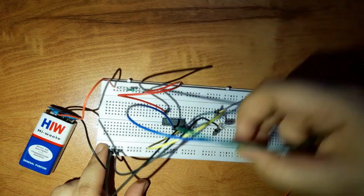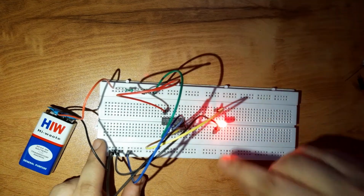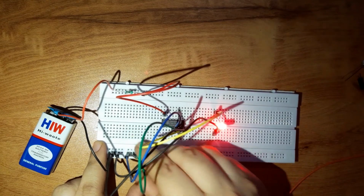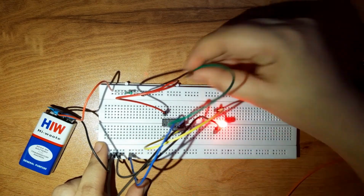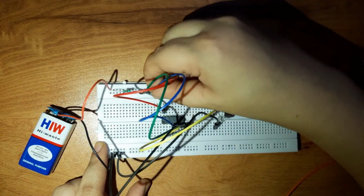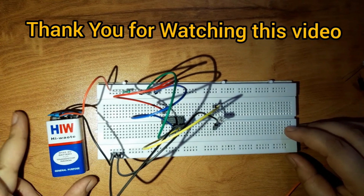Exchanging these inputs, this input low, this input high, it is still glowing. If both the inputs are low, it will glow. When both the inputs are high, the NAND gate will not glow. So this is how the NAND gate can be implemented on a breadboard.